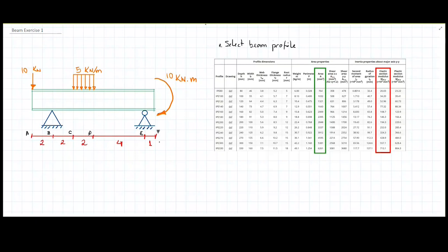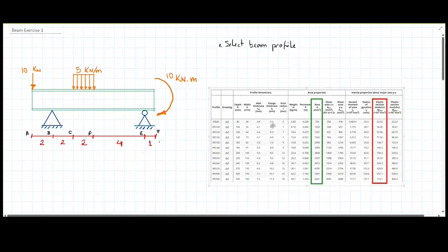Better said, estimate the largest deformation on the beam and see if that is larger than a certain parameter we're going to give, or restriction we're going to give. It is pretty common for beam selection and design that the deformation of the beam, the largest one, the maximum, has to be smaller than a certain number here.